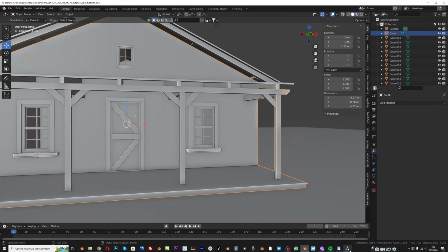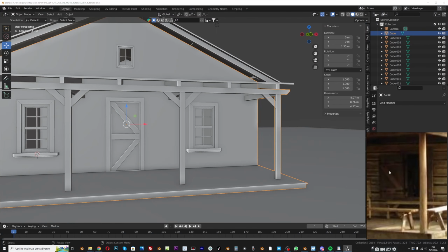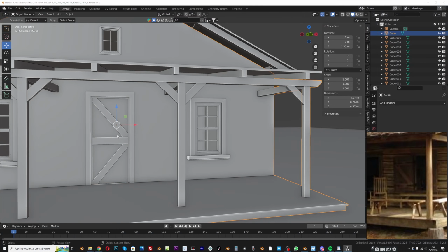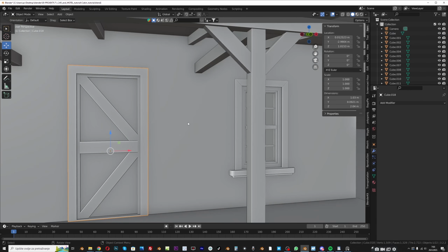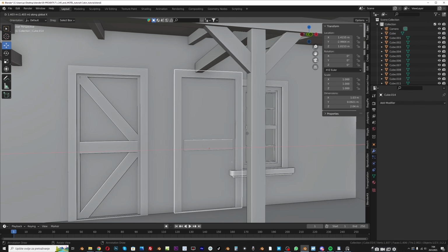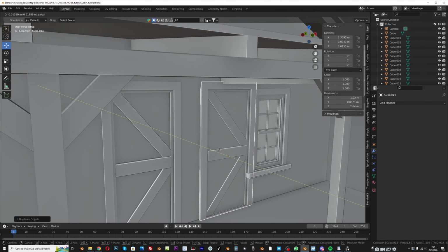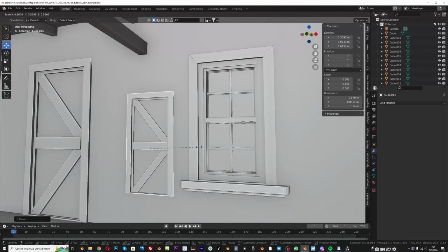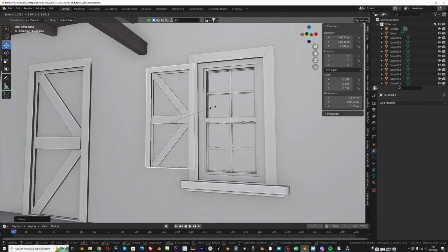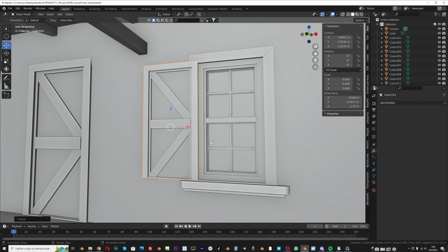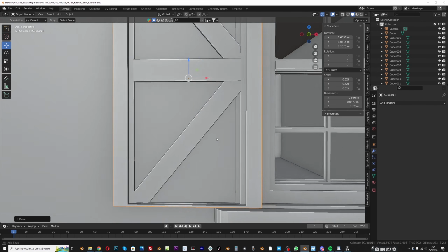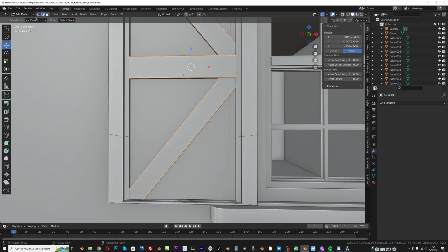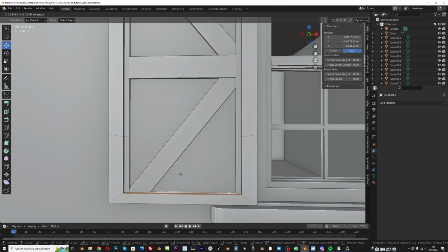And we can try create these window shutters, and you can see that this is similar like door. So I can try duplicate this door and use this as shutters. So I will go with Shift D and move this on X axis, then move this on Y axis also and scale this down. And I will try fix this part down, so we can go to edit mode, face select, and we can grab these two face and bring this up.